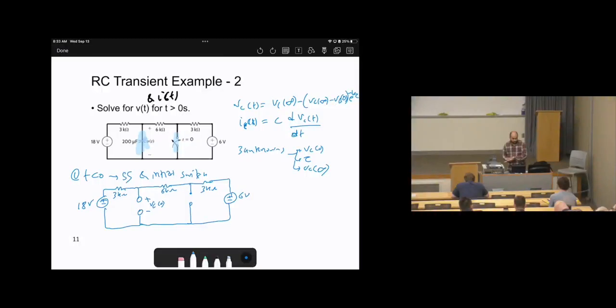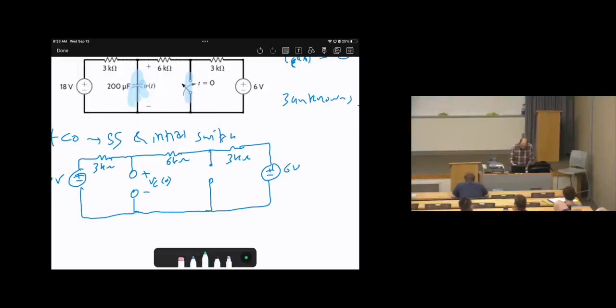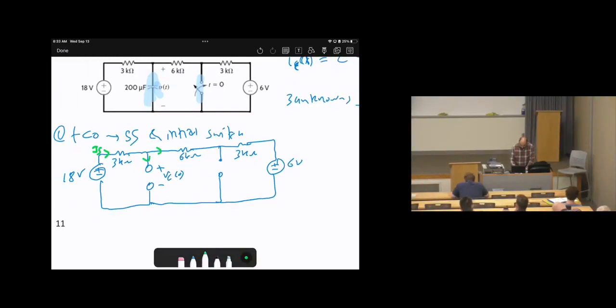So by looking at this circuit, let's label the currents. Here is I source. Do you think the current will split? No, because the current requires a closed path. So here I equals 0. Here it continues as I source. Do you think the current will split here as well? No, because it is an open path. The current needs a closed path. Therefore, we realize that all of this loop shares the same current.